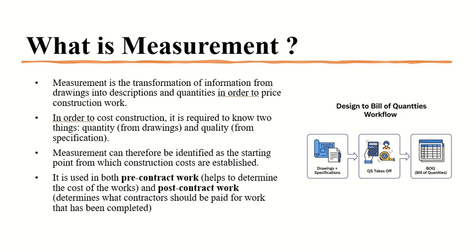Why do we need post-contract measurements? Why do I need to calculate quantities post-contract? The contract is already given. Do it. Why should I go into calculating the BOQ again? What's the difference between pre and post? Okay, to see the difference between pre and post. Maybe an item you mentioned in the pre-contract was priced cheaper, and now the contractor is spending more on it. So it gives you an idea about cost control. How is he managing the budget?